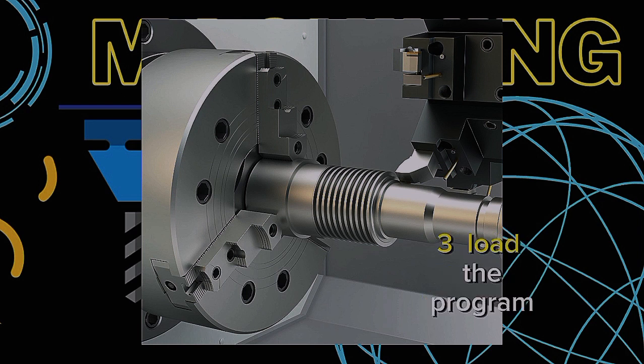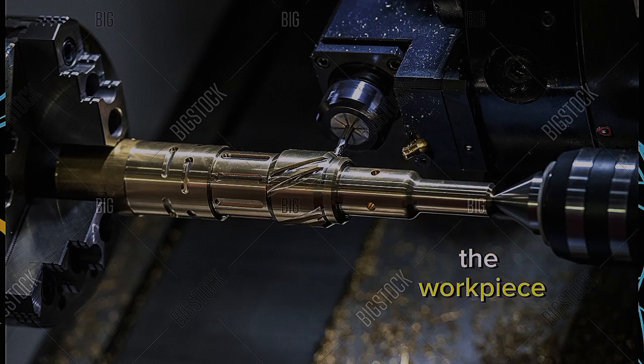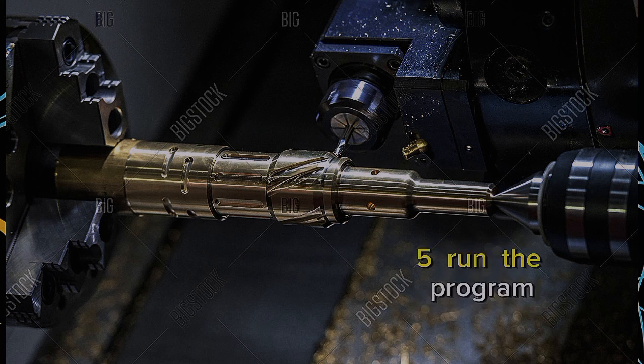3. Load the program. Once the design has been converted into a format that the CNC lathe machine can understand, you will need to load the program onto the machine. 4. Set up the machine. You will then need to set up the machine, including the tooling, the workpiece, and the cutting parameters.